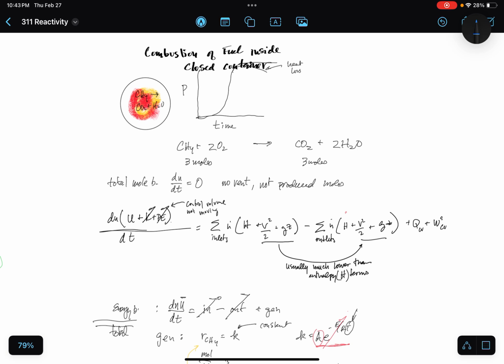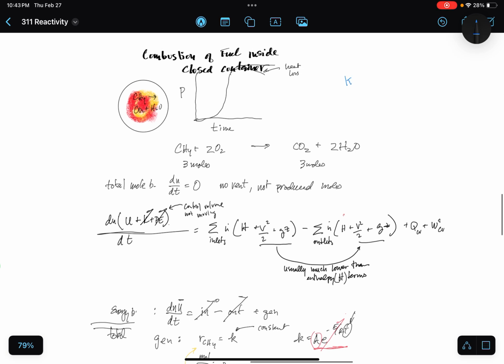And we talked about the KST value, and the KST value, that's typically for dust, and that is the change in pressure with respect to time. That's a maximum times the volume of where that pressure was measured to the 1/3 power. And KG is for gases. And you'd have a plot similar to that, and this dp dt max is right there.